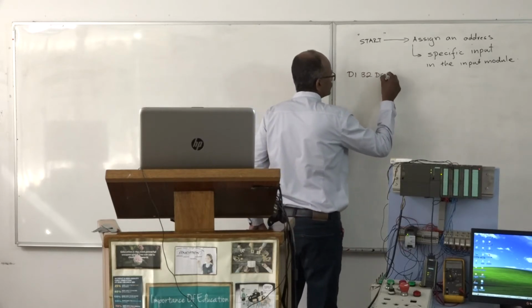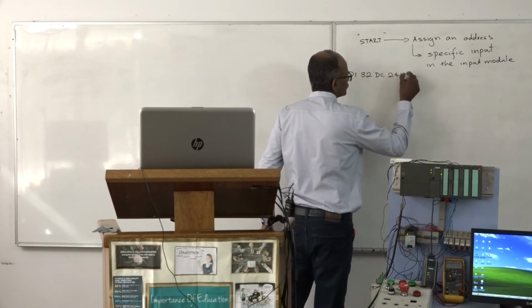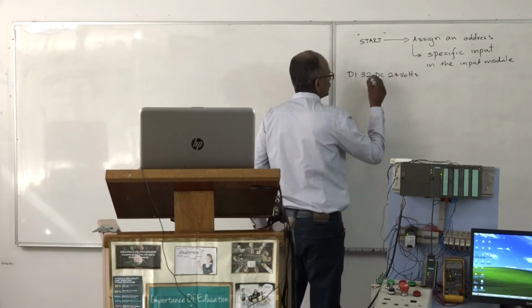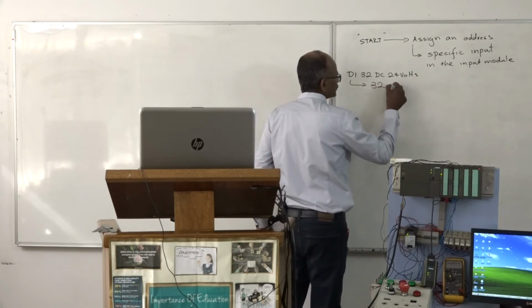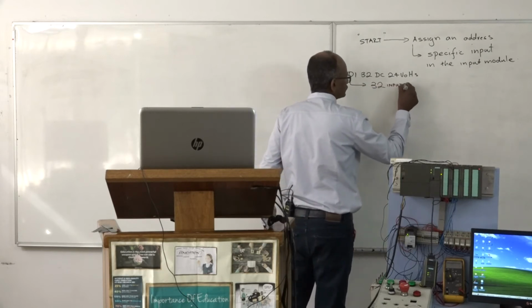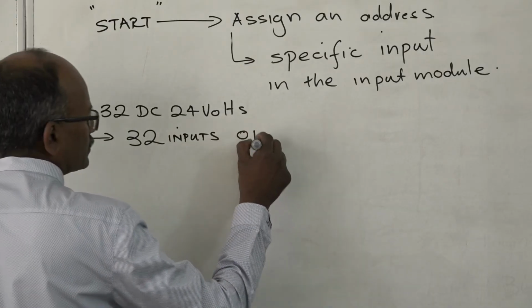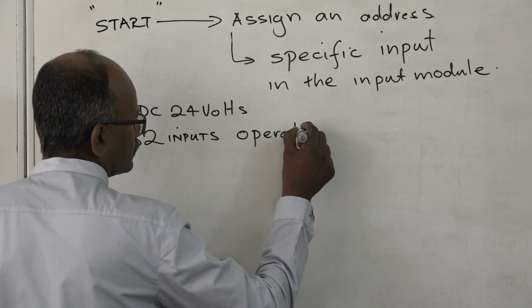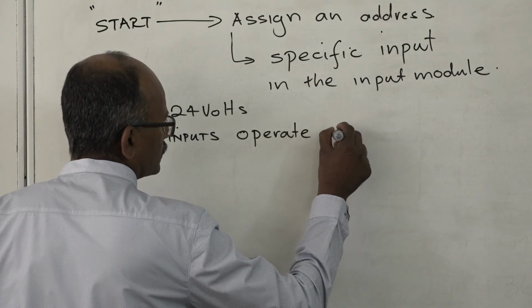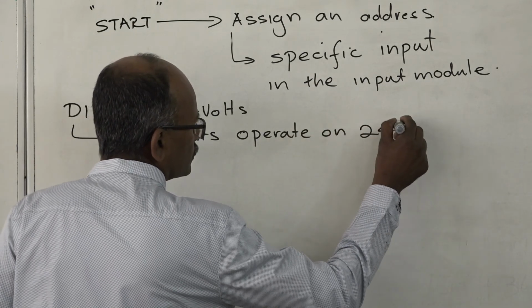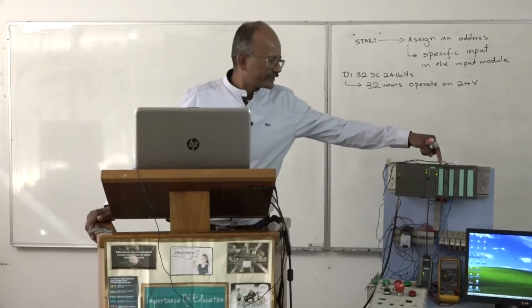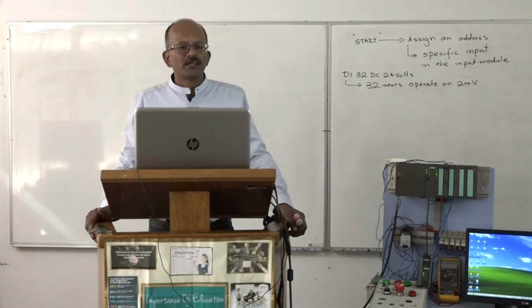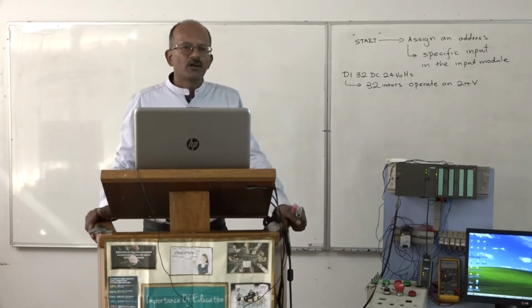What this means is it actually has 32 inputs that operate on 24 volts. The particular addresses for those inputs are assigned in your hardware.